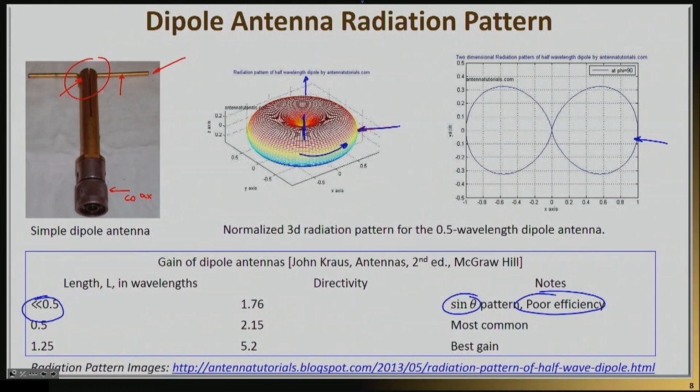So electrically small antennas, meaning antennas with electrical length much less than the wavelength, are fantastic from a form factor point of view because they can be mobile, but they're horrible from a point of view of efficiency. Sometimes that's the only thing we can do.